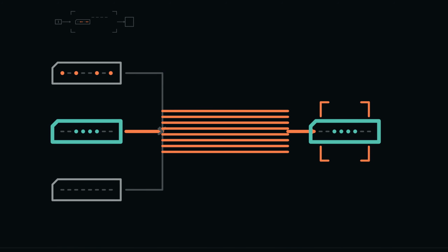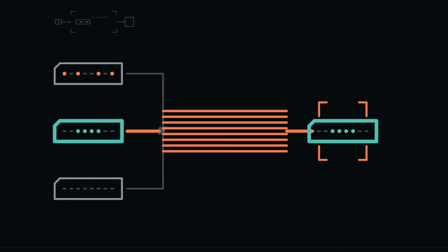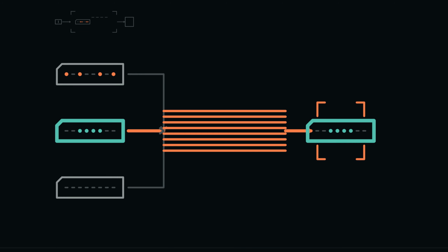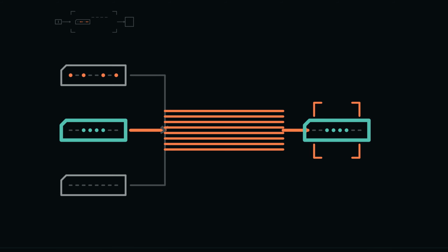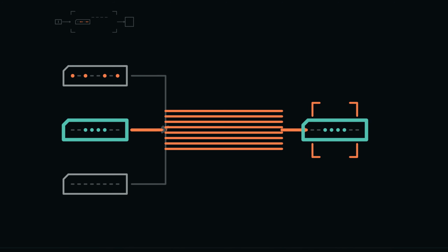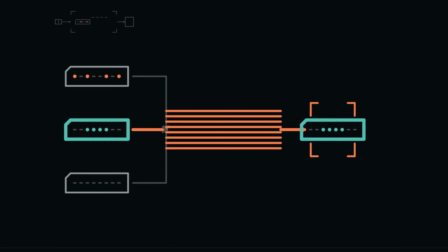Each bus line has a declared position from bit 0 through bit 7. Bit 0 does not become the most significant bit because its wire happens to be drawn higher or closer to a register. The diagram's geometry helps us follow connections. The wiring contract determines significance.